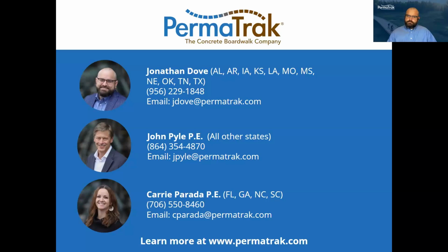So what do you ask the geotechnical engineer to do? Take these loads, provide for us, the designer and the boardwalk engineer, give them design recommendations. For example, let's have them evaluate, can the boardwalk be built with a shallow foundation system? Yes or no? If yes, give us an allowable bearing capacity of what that footing can be designed for. If that option is ruled out and it needs to be a deep foundation system, make a recommendation on what regionally is a good material for the pile foundation system.